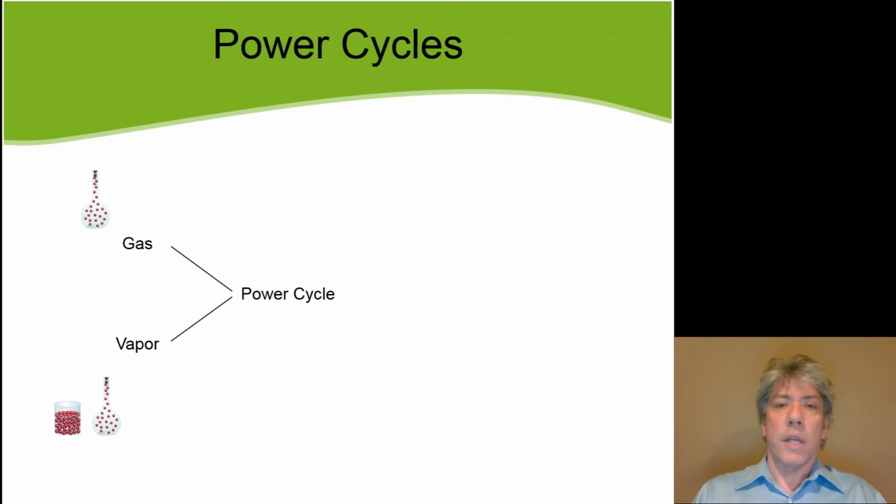It's hot nitrogen. The only purpose of the gasoline, or in my case the diesel, or in someone else's case the natural gas, the only purpose of that flammable fluid is to heat up the nitrogen, to make the nitrogen hot, give it thermal energy by converting chemical energy into thermal energy so that that nitrogen can push the piston down doing work. So the working fluid in your car's engine could be argued to be primarily hot nitrogen. That could be argued as the working fluid, and of course that nitrogen never goes into the liquid phase.